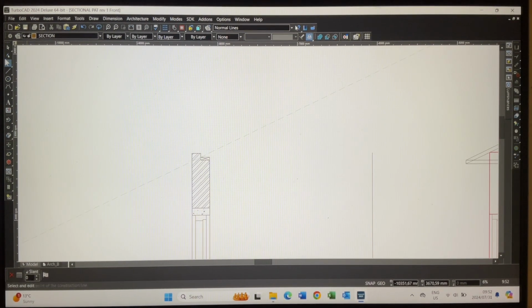The roof truss that I'm going to use is 144. So I'm going to go over here, press parallel lines, tab 144, press enter. Click on there, go up there. Draw a line going across over here. Go to the parallel lines, still 144, so click on there.